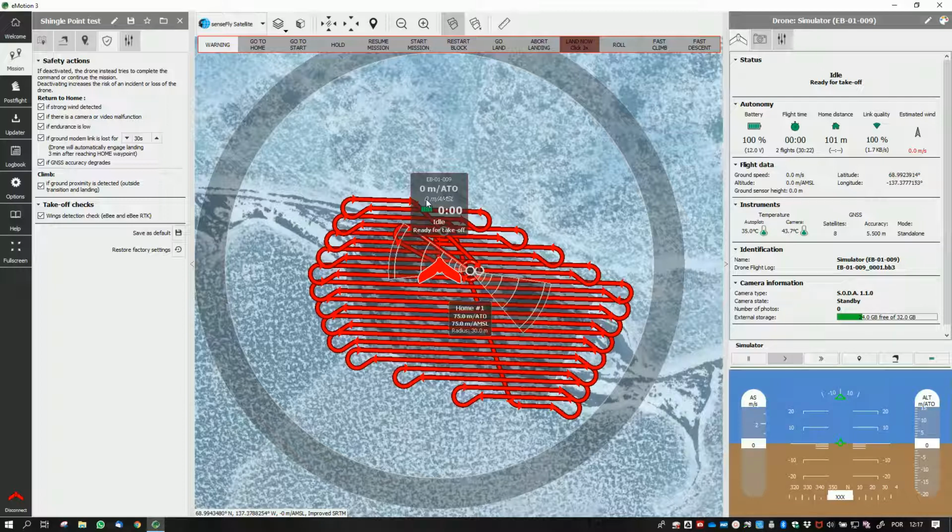And just remember, when plugging and unplugging the camera from the drone, you should always have the battery off. So the drone should not be connected. Any cables that you are plugging into the drone, no battery. Also for downloading data, battery out and drone off.